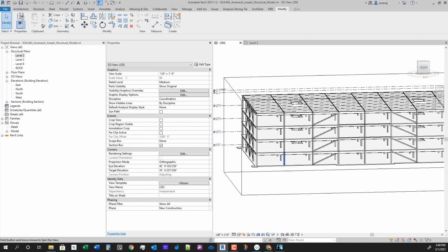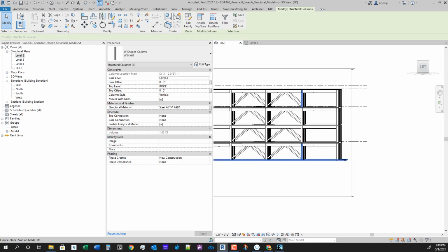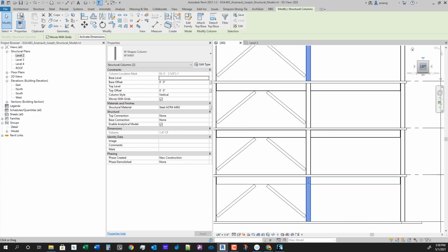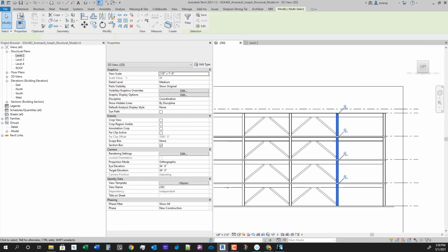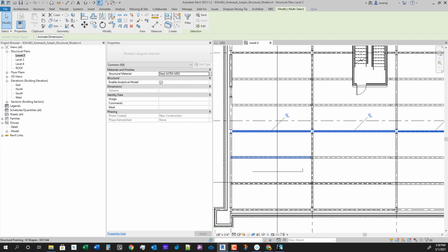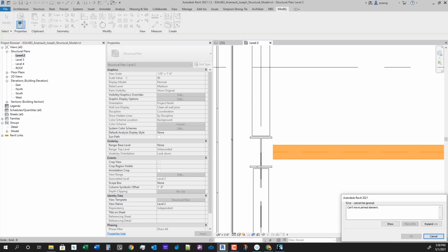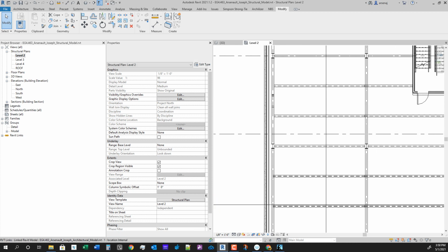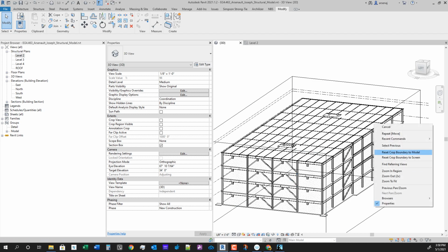Go back to the 3D view, pan around. I'm going to select the top and the bottom column. Select my view cube face for the left or right, whatever one you're at, and window over, kind of pan around to see I've got everything. And then we'll move. Can't move pinned element. Oh yes, I think because some of these are beam systems, which is fine. We'll just select previous.